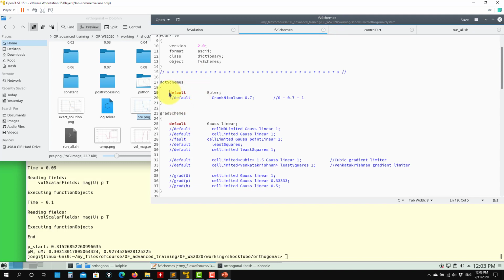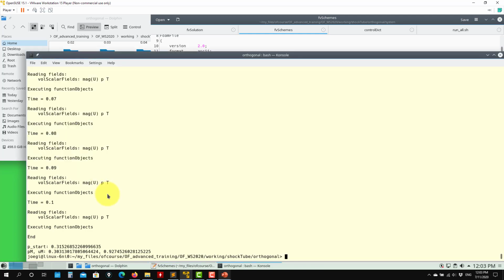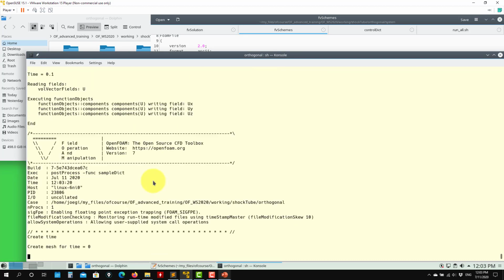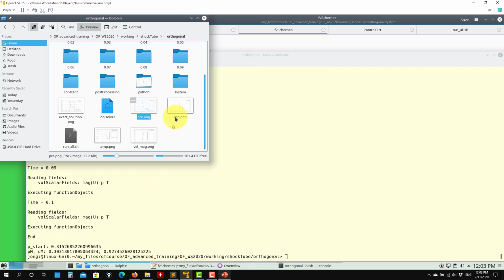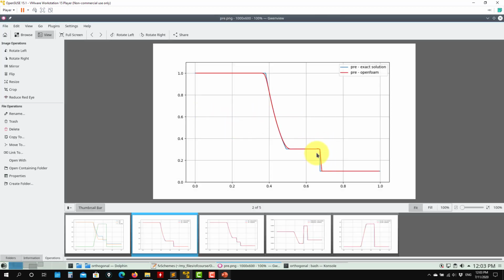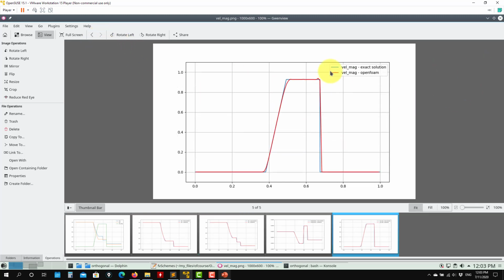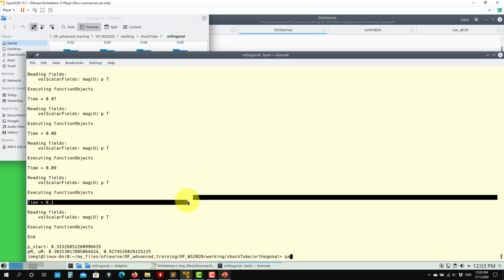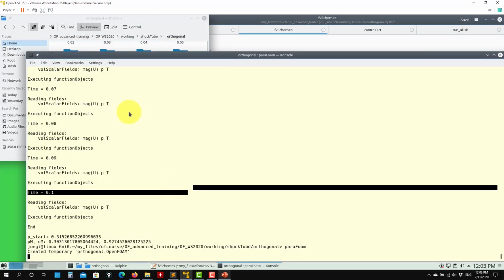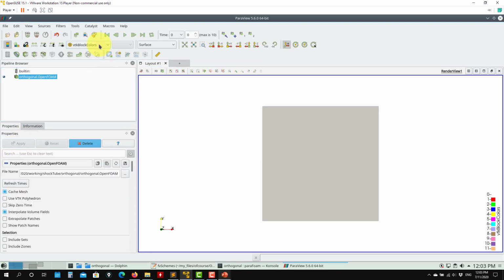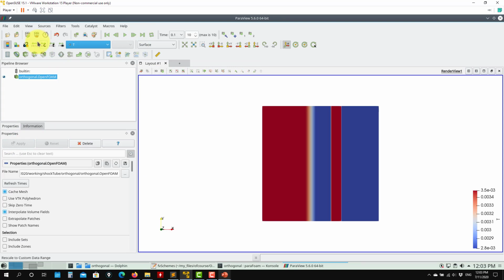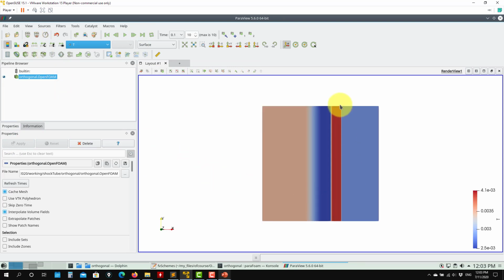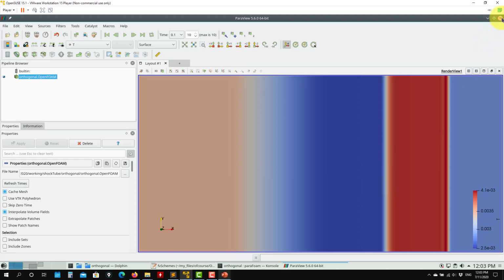Okay, so now let me go here and change my time discretization. So remember, if your CFL is less than 1, Euler is okay, but if you want extra higher accuracy, you can go for a second order. So here, let me use Crank-Nicolson. That also tends to be a little bit oscillatory. Let's see what happened here with the Crank-Nicolson. See that now I start to see more oscillations. Okay, and you have it there. So if we plot the solution, we might see somewhere here, yes, see that you have your oscillation there.